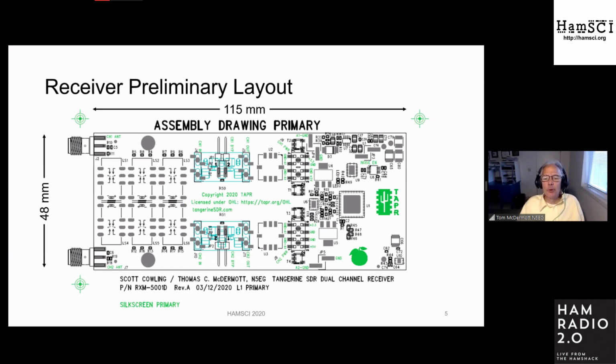And then it goes through a U2 filter, which is a roofing filter. It's a 55 megahertz low pass filter module. The spec says 40, but the roll off is pretty gentle. It then goes through a power and ground header. The active filter module will plug on to not only the filter input and output connectors, but also the power and ground connector. So the active filter module is larger than the passive, so that it can pick up the power and the ground connectors over here.